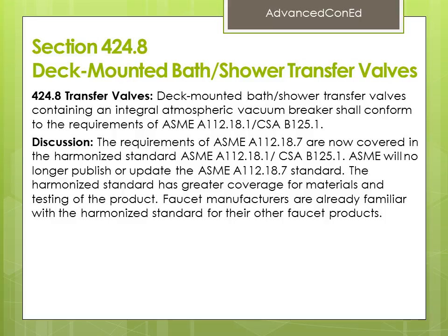Section 424.8 Deck-mounted bath shower transfer valves. 424.8 Transfer valves. Deck-mounted bath or shower transfer valves containing an integral atmospheric vacuum breaker shall conform to the requirements of ASME A112.18.1 or CSA B125.1.